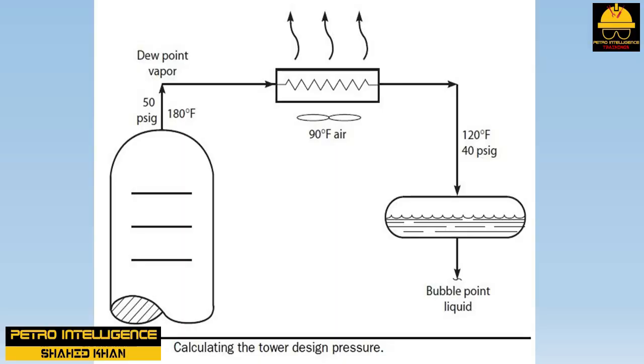Another reason to raise tower pressure is to permit higher reflux rates. If the pressure controller in the picture is set too low, then during hot weather, when condenser capacity becomes marginal, the level in the reflux drum will be lost. If we then raise the pressure set point, the drum will refill. But why? Raising the tower pressure also increases the reflux drum pressure, raising, in turn, the temperature at which the vapors condense.